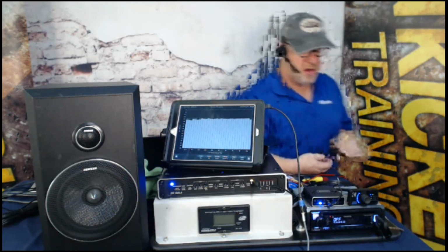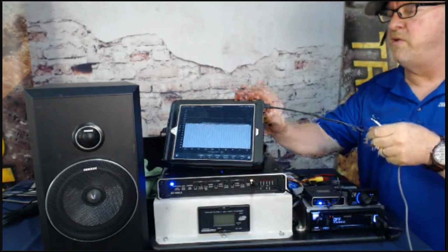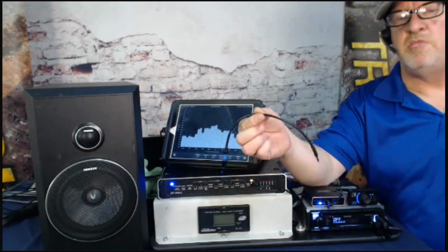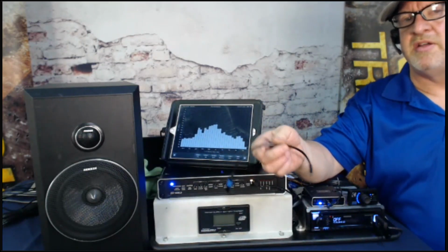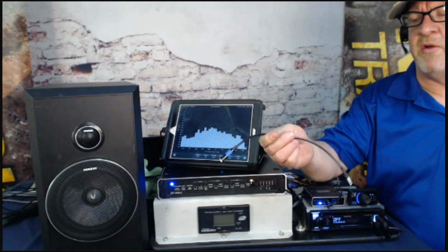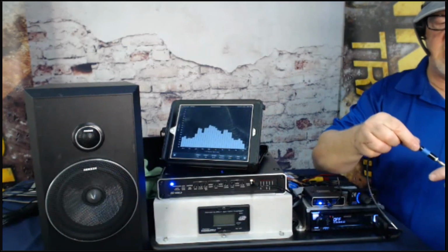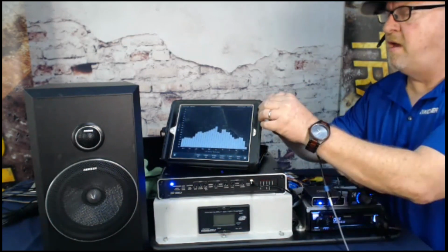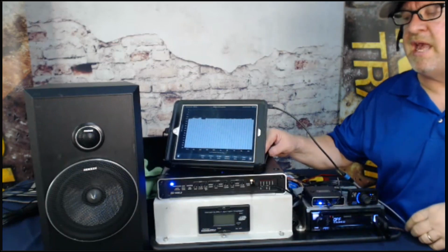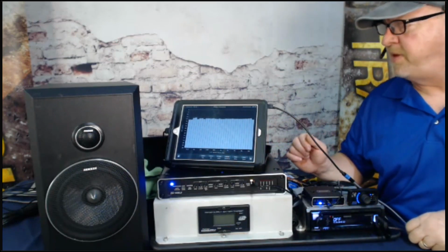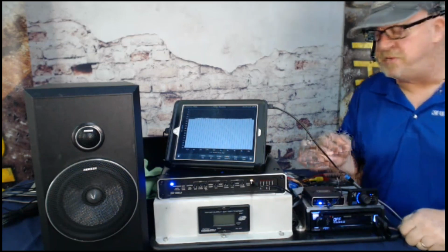Just remember, if you're going to do the home built RTA like I showed, this is your most important cable. That is the line to mic adapter. It sells for about 20 bucks. If you find one online that's $3 or $4, it's probably not going to have the resistors or the microphone input. But this is the key that makes this work. We literally plug it into the 3.5 jack on the headphone, and now I can probe any speaker lead out of any radio, any amplifier, factory or aftermarket, and know exactly what signal it's producing.